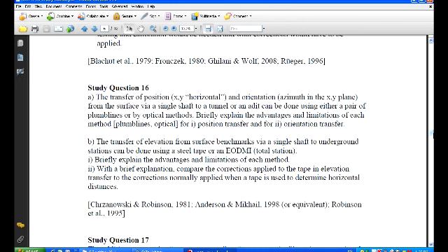process in which you would set the telescope of the total station to be at 90 degrees and try to line up a leveling instrument with it so you could transfer from the center of the instrument over to a leveling staff. And this is a bit of a challenge because of the difficulty in focusing at the crosshairs of the two telescopes. You can do that if you have autocollimation eyepieces that will allow you to look through the eyepiece and also project the image of the crosshairs out to the other instrument.